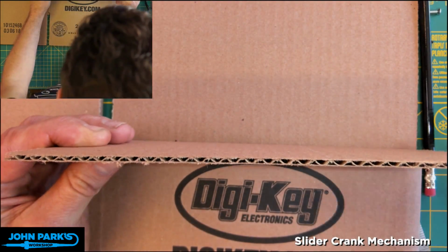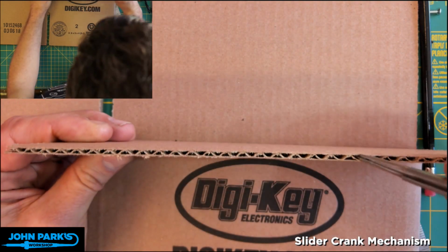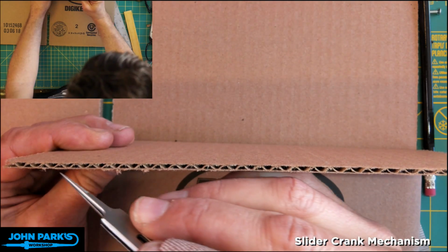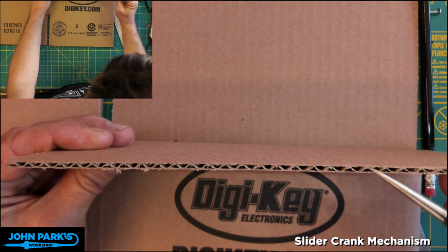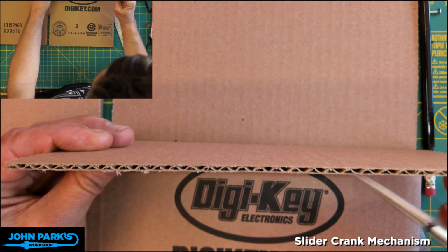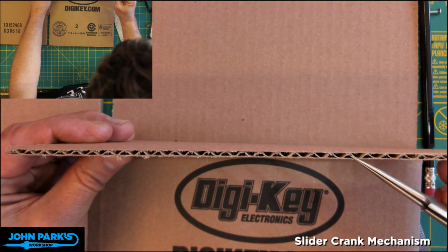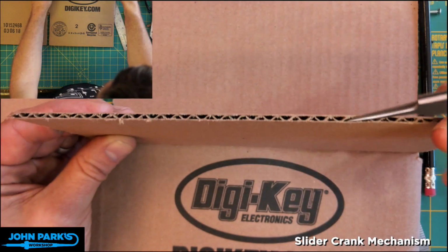You can see we have a facing material, which is pretty much the same thing as our paperboard or chipboard. And then we have this row, this inner wall of flutes is what these are called. These are these corrugations. And this wavy pattern is particularly strong structurally. It's a brilliant design, honestly. It's why it's been around for a long time and it's so ubiquitous. And then we have a second face.